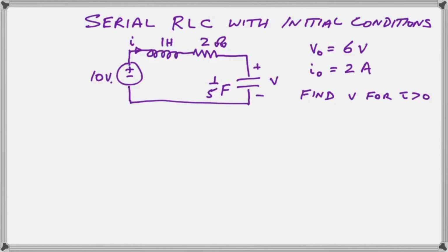So that means after the switch is thrown, there will be a further increase in the charge on the capacitor from 6 volts up to the maximum of 10 volts, at which time the current will cease entirely. So we are going to solve that problem now with a mathematical expression in terms of time. And that is why it's called transient or time varying behavior on a DC circuit.